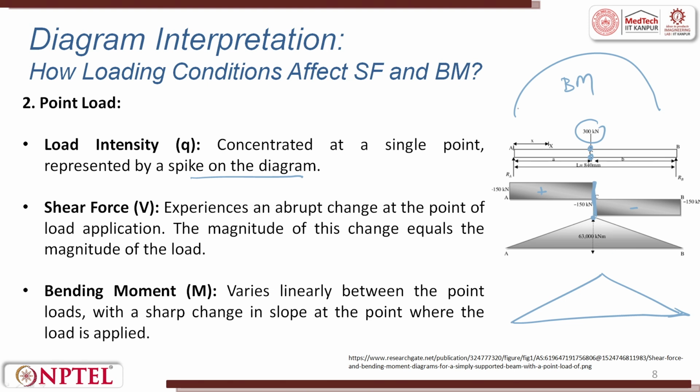In some cases, it is also interesting that you can convert this UDL into a simply supported case for calculation simplicity. You can see here this will be the additional area, but you can try to generalize it if you want. When there is a complex situation, you can try to do that.